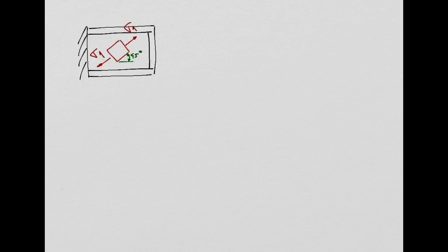So this is the direct stress that is being carried in tension with an angle of 45 degrees. This is also known as a pure diagonal. I can write here, it is better. This is known as a pure diagonal tension field.